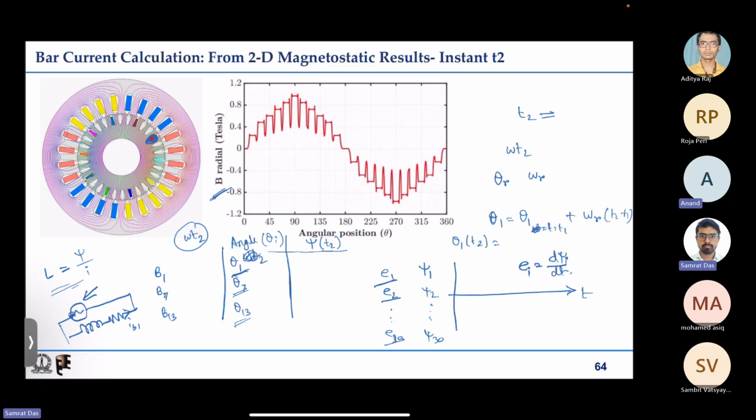Just a minute. The thing is, I have my stator flux direction and also the rotor flux direction, right? It is 90 degrees apart from each other for an induction machine in this case. Now, whatever I can see on the diagram at this point of time, between the yellow and the blue color, there is a flux direction, either upward or downward, based on my conductor position, correct? That is my rotor.